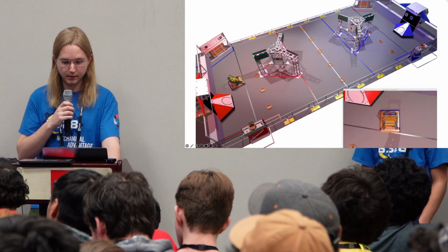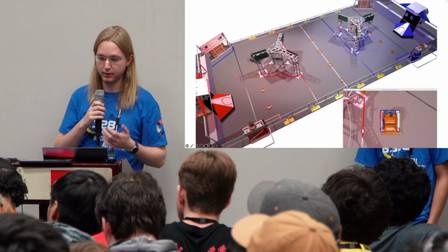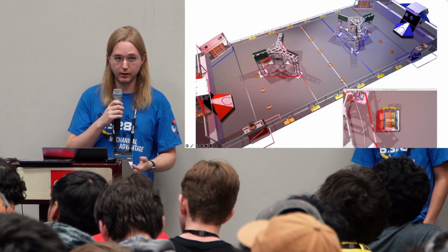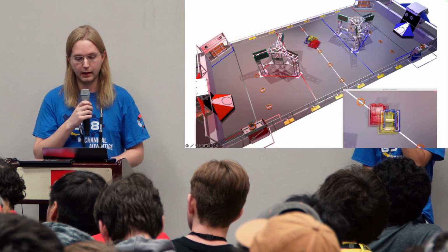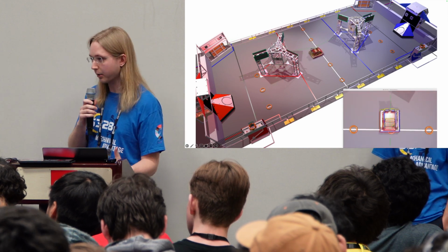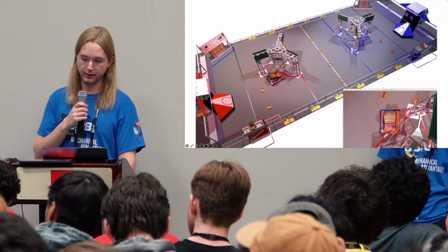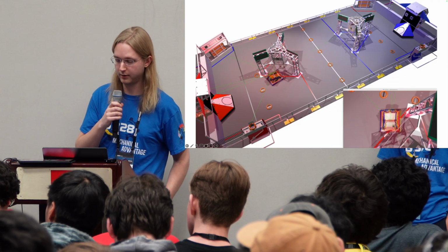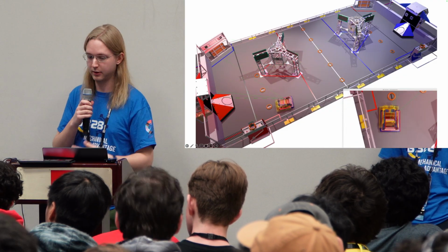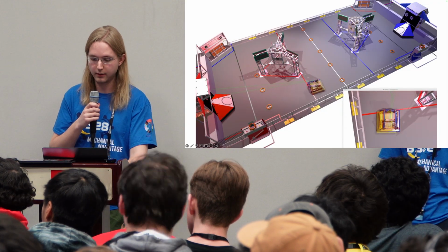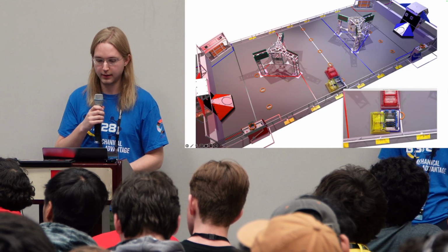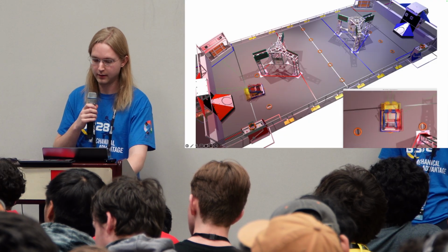Okay, here's another fun example. We can use log replay to improve our localization algorithms. We've been revising our filtering for several years for April tag localization, and over that time we've developed a variety of different algorithms. We can use log replay to check how much those algorithms are helping us. In this case, the solid robot is our standard pose estimator, and the yellow and red robots are alternative setups that we might be trying out. So we can confirm which of these estimates are more accurate and which of them are jumping around unexpectedly.